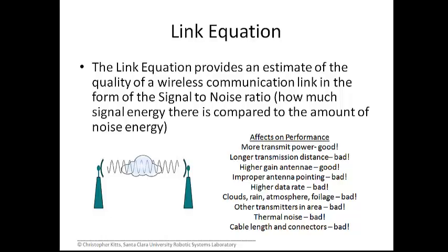Without going into the mathematics yet, our intuition tells us a lot about what's good and bad for the quality of our communication link. And there on the bottom right, you can see a whole slew of considerations and if they're good or bad for us. So I can imagine broadcasting my signal with more power, and that's going to be good because I'm investing more energy in the portion of the link that I want, the signal.